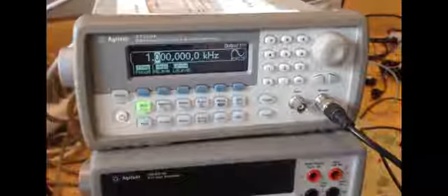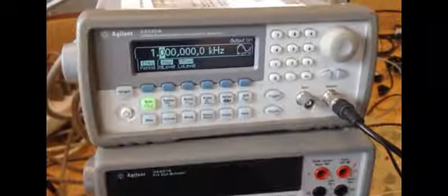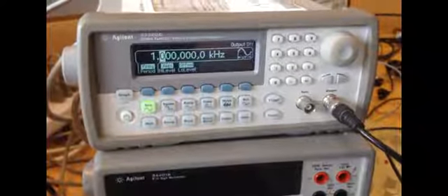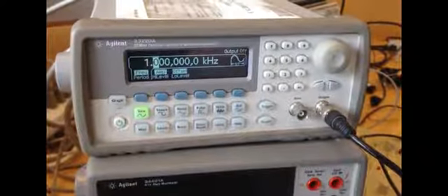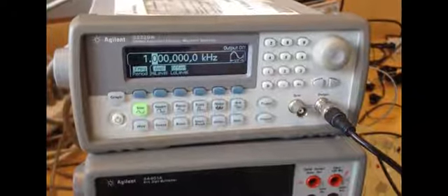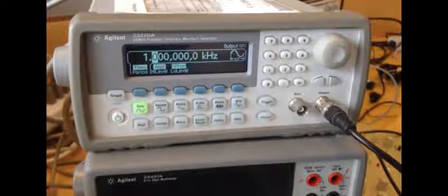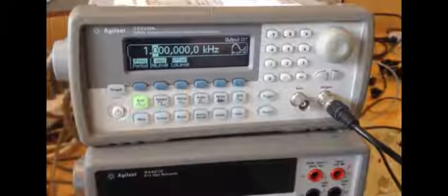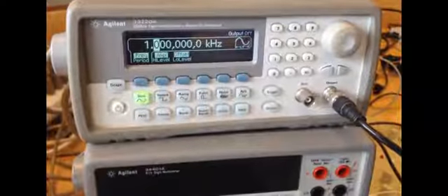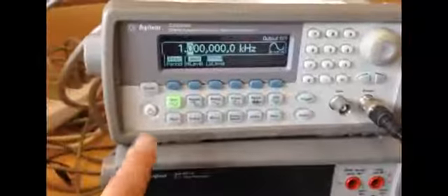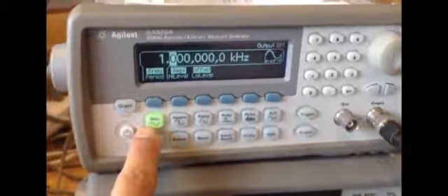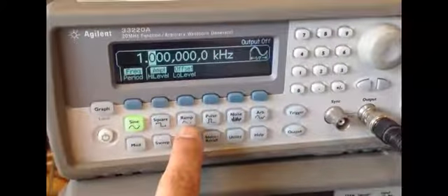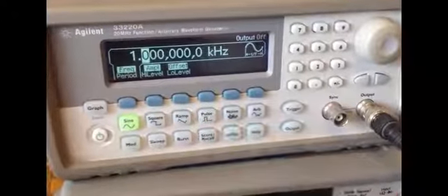in this part I'm going to show you how to use the function generator to generate the AC signal with the power supply that we talked in the previous part. You could only generate the DC signal, but if you need alternating source of voltage, then you need to use the function generator. So when you turn on the function generator, as you can see, the default is going to give you a sine signal, but you can switch to a square or ramp, which is a triangular shape of the signal, a pulse, or even generate noise.